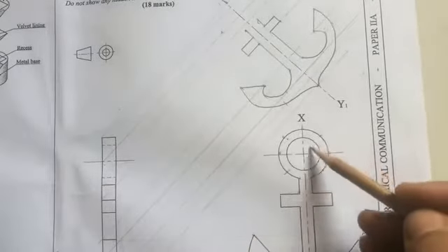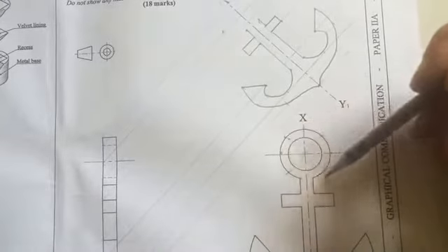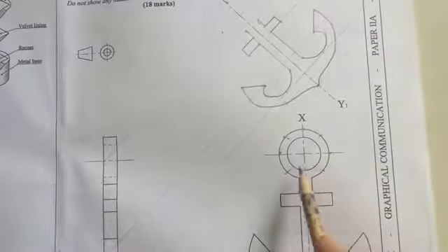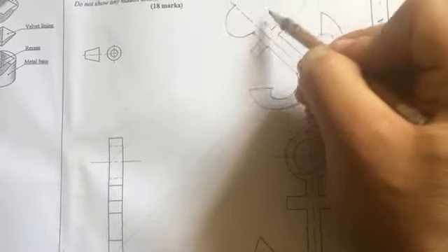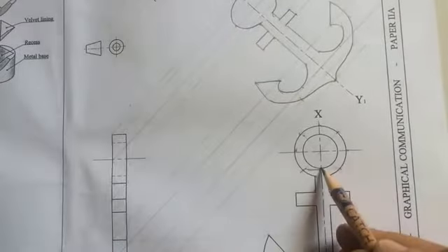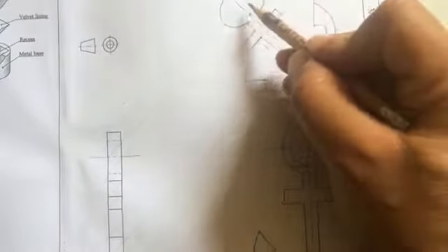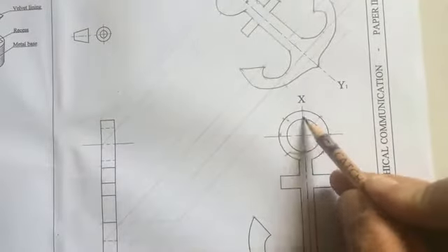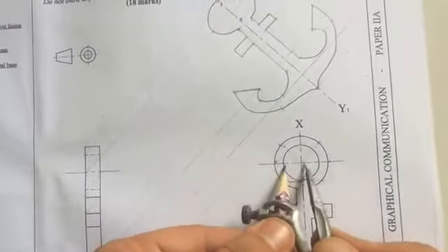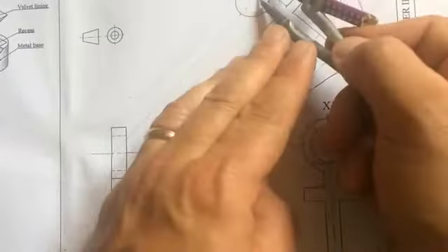I could use extra points for the circle to help me get a better freehand. So a small circle like this would be enough to have an extra 4 points projected to the front face and then find the perpendicular distance for that. But for the sake of this exercise I'm just going to draw a freehand curve there. The same way you'd need to find the inner circle. So that's the top 2 points exactly on the XY line. The distance, the thickness of the circle is taken from here, that way and that way. So for small circles there's no need to get 12 points like we usually do with a circle.